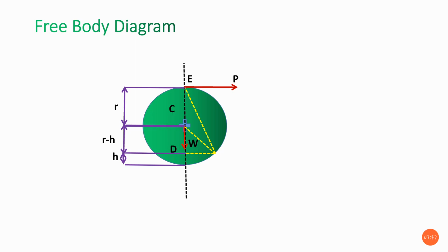So it is clear where the reaction force is generated: not along AD or AC, but in the AE direction. That's because the weight's line of action is vertical, and P acts in the horizontal direction, and their intersecting point is E. Then your reaction force develops in the direction where these three forces intersect at point E. Then we can say these are concurrent and coplanar forces, and the body is said to be in equilibrium.